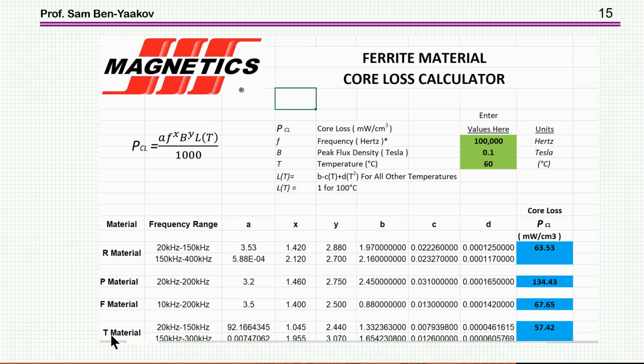Same thing goes for a ferrite material. These are ferrite material, and here are the coefficient x and y. This is x and y. These are the power terms here. And we see again that here we are talking about up to 3, the y here for the B, and x is 1.5. These are again experimentally fitted coefficient, which imply that the basic original Steinmetz equation is not very accurate if you take into account practical material.